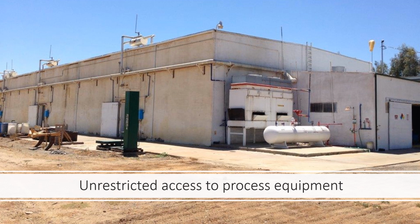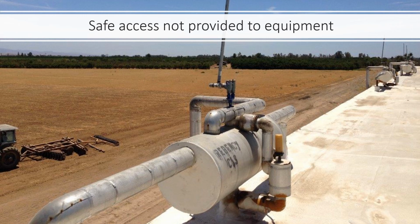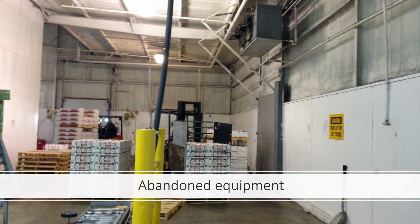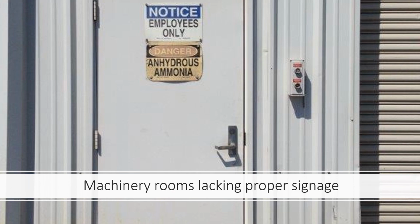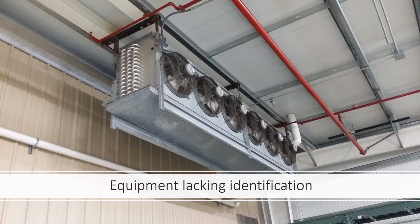high-risk process equipment that is located in an area that is unrestricted and therefore accessible to all employees and visitors, machinery rooms being used for the storage of equipment and supplies that could negatively impact the system, equipment that cannot be safely accessed for regular operation and maintenance, abandoned equipment that remains connected to the system, machinery room doors that lack proper signage, machinery room doors that do not swing in the direction of egress or are not equipped with panic hardware, equipment that lacks proper identification,